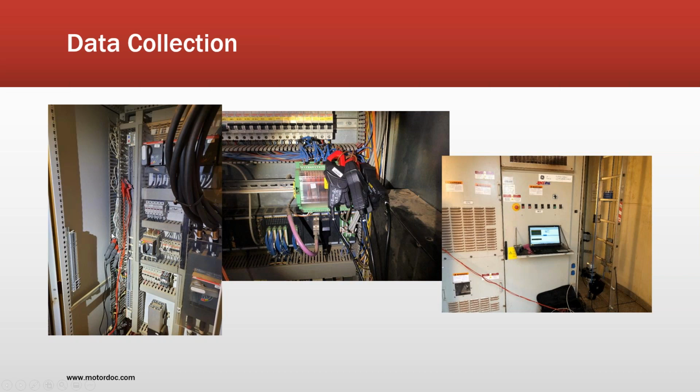We've identified where to get good data off of the low power cabinet. So in many sites, we don't even have to turn the towers off anymore if we're doing data collection. Those are the same points that we would gather data for the continuous monitoring device. The one in the middle, that's an S88. We take it right off the green box. Top is current, bottom is voltage. All we have to do is match up.